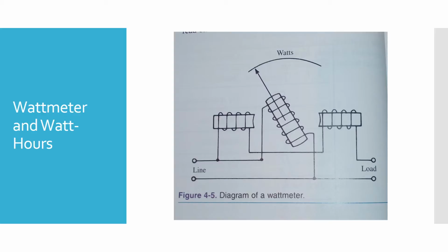While a wattmeter measures the instantaneous power used in a circuit, a watt-hour meter measures the amount of power used in a given time. It is installed by the power company on the outside of your home or business. Since the watt-hour is a very small unit, the standard utility meters read kilowatt hours, or 1000 watt hours. The number of kilowatts equals voltage times current divided by 1000, or E times I divided by 1000. Electric power consumed is purchased at a rate per kilowatt hour.